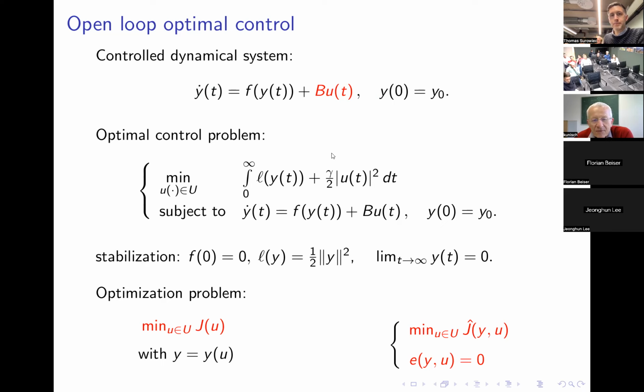Instead of solving the original optimization problem from 0 to infinity, you solve on a very short time interval, open loop, you stop, you solve on the next time interval, you stop, and then you concatenate. So piece by piece, morceau par morceau. Okay, we do that.